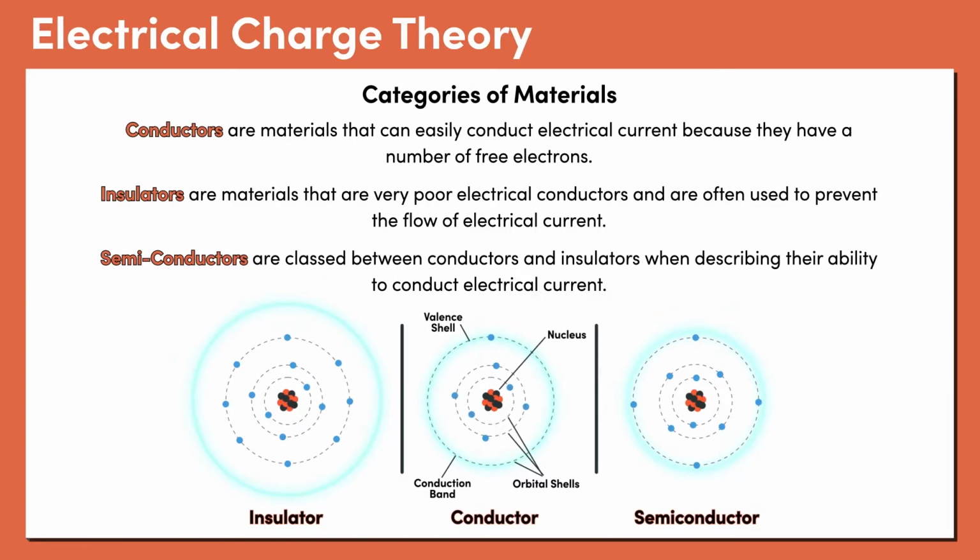We do have something in between, and we call them semiconductors. They are really important for electronics. They have 4 electrons in the valence shell. In addition, we can manipulate this number by doping with impurities, so we can go to 5 or even 6 electrons, or down to 3 or even 2. And this changes the overall properties of the material and it becomes N-type or P-type.